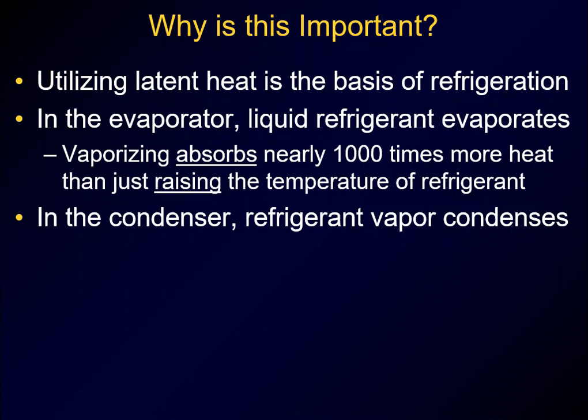And when it does that, it has 1,000 times more capacity. Remember what BTUs are. A BTU is a quantity, an amount, right? So think about it like, if I were to catch all that heat in a bucket, how big a bucket would I have to have? Well, if I can put it through this latent change, the bucket doesn't have to be nearly as big because it has the ability to hold a lot. So it's not just raising or lowering the temperature, it's going through that change of state that really does the